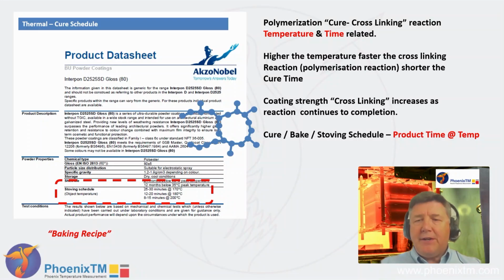In the coating industry today, the use of through-process temperature monitoring has become very important in maintaining the quality of both powder and painted coatings. Understanding the temperature of your product as it travels through the curing oven is essential to ensure that you get the right thermal conditions to cure that coating properly.